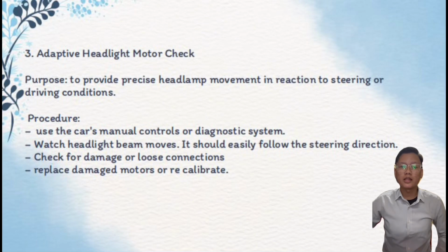Watch how the headlight beam moves. It should easily follow the steering direction. Check for damage or loose connections on the adaptive motor and its connectors. Using the instruments suggested by the manufacturer, replace damaged motors or recalibrate.